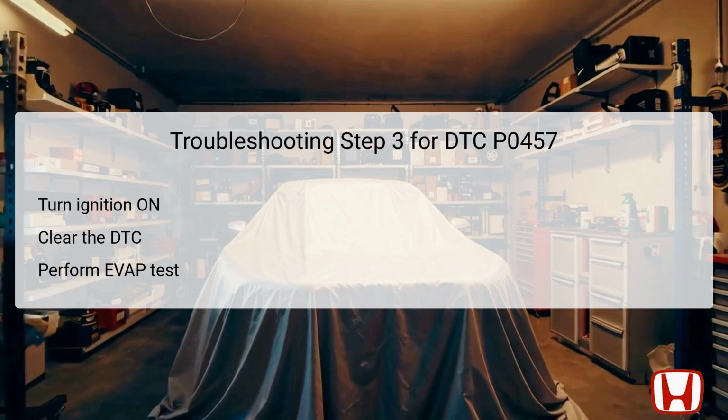Once cleared, proceed to select or input the EVAP test function in the inspection menu to check the performance of the evaporative emissions system. The outcome of this test will help determine if the system is functioning correctly. If the results indicate that the system performs well, it may point to an intermittent failure that requires looking into poor connections or loose terminals at related sensors.